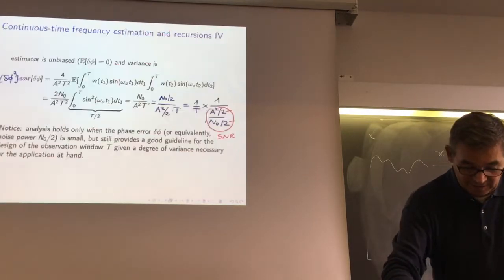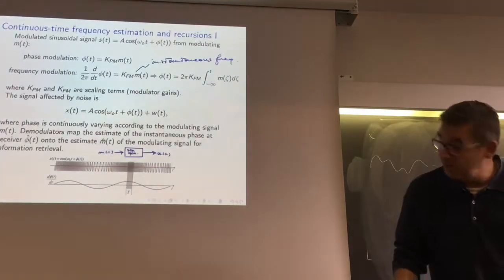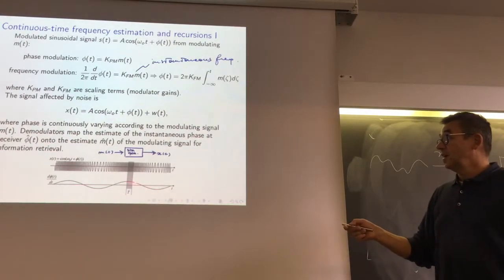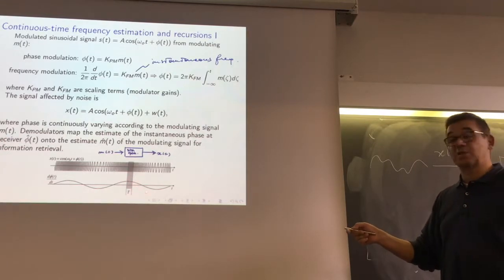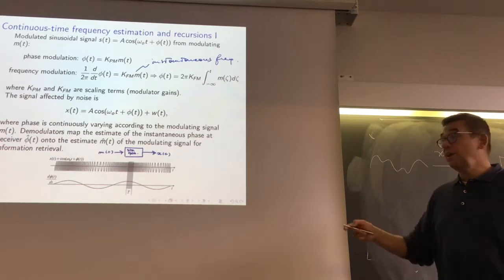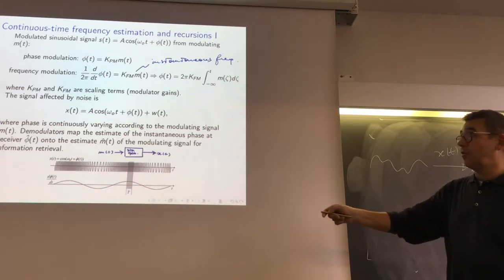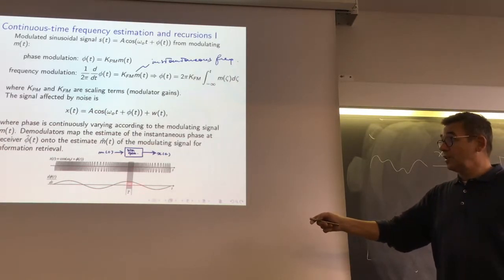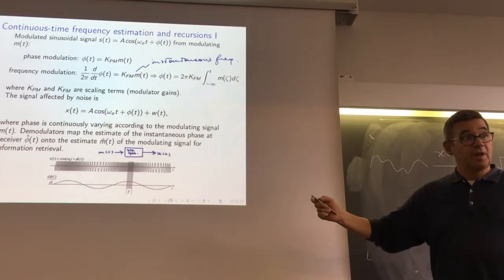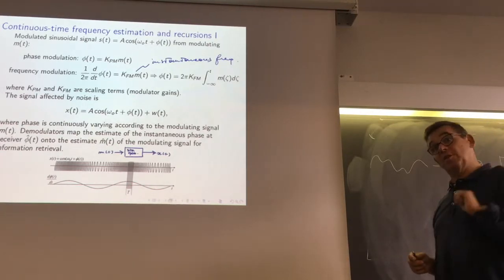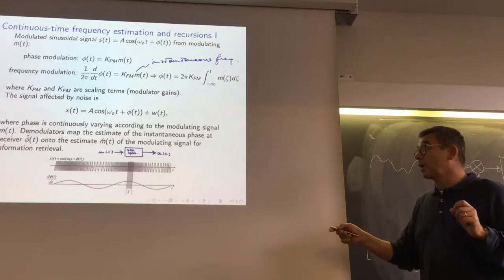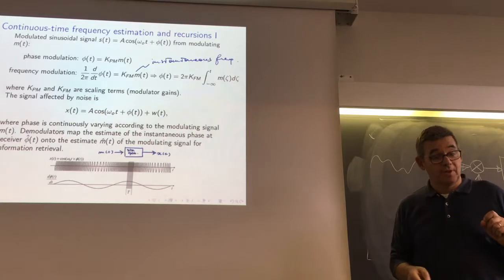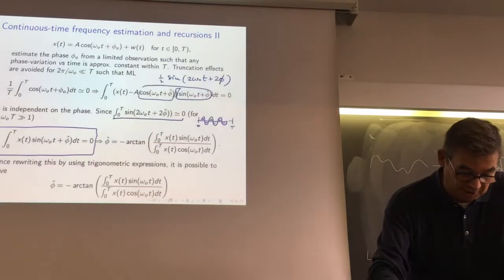So this capital T interval depends on how fast the frequency or the phase is changing. If the frequency is very slowly varying, then you can take this capital T very big. In the electronic world, this means that the band of the modulated signal should be very small compared to the frequency which is oscillating there. Usually the number is 100 times.